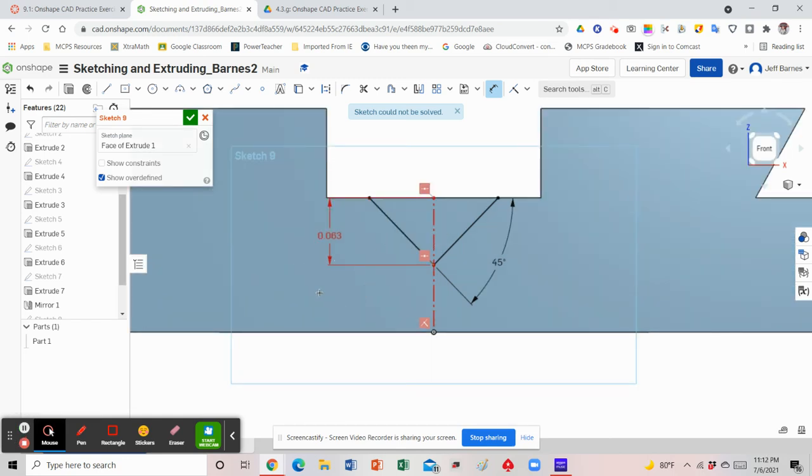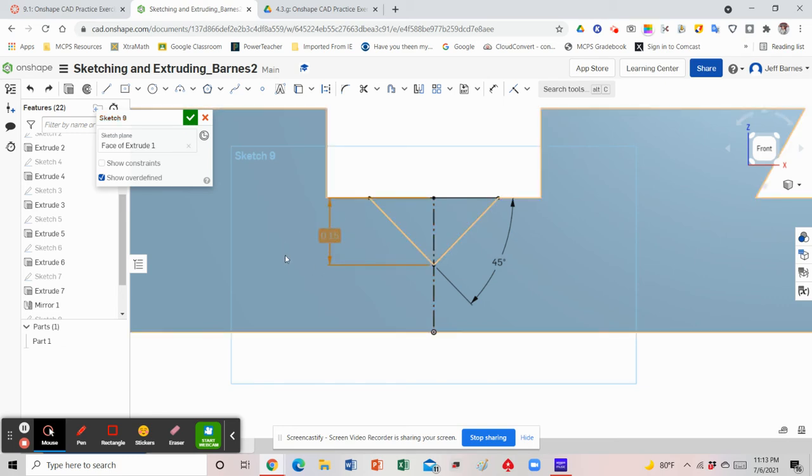Okay, it looks like I've run into a little bit of an error here when I was trying to make the correct distance of the base of my triangle here. So we obviously can't have anything that has a red error like this. So I'm going to go ahead and fix that. So you can either hit the back button or just delete the dimension. So Control Z, because I don't want that. Okay, and I'm deleting that little grayed out dimension there.